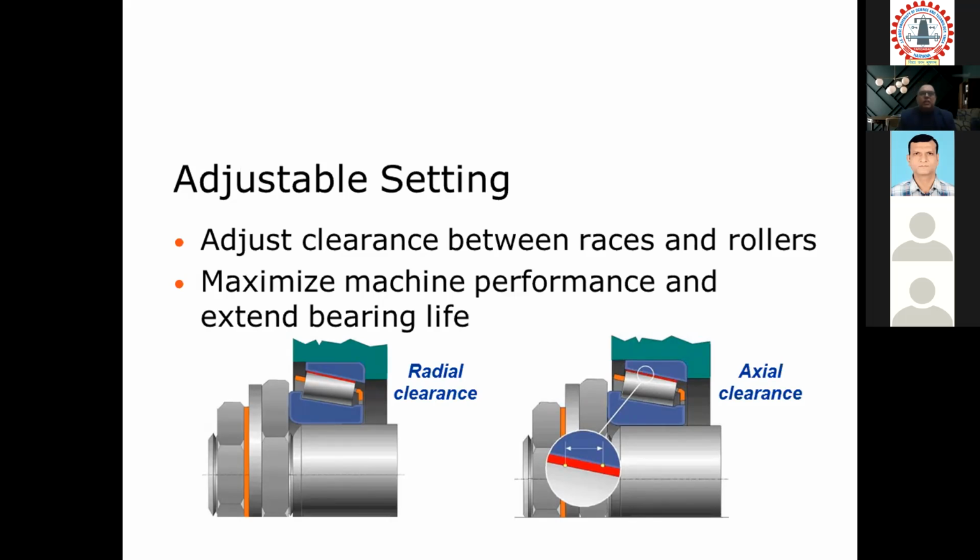So the lubrication again depends on the application, which is the load parameters, speed parameters. On high load, there are extreme pressure kind of lubricants which are available. There are normal industrial oils and greases which are available. Again, type of lubrication can be grease lubrication, oil lubrication. Again, it is the ease of application. So it is recommended by the designer of the bearing.